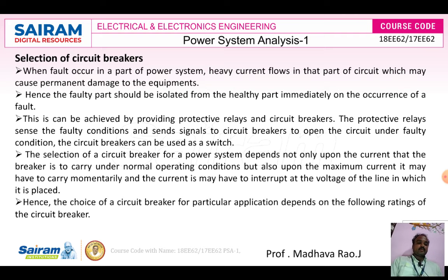If you are using it for power generation or for your home, the circuit breaker rating and capacity are different. So we need to choose the circuit breaker based on the application. Suppose you are using it in homes, the circuit breaker size and rating should be very small. Suppose you are using it for power transmission in a substation, there will be heavy voltages and heavy currents, so we need to choose high rating circuit breakers.